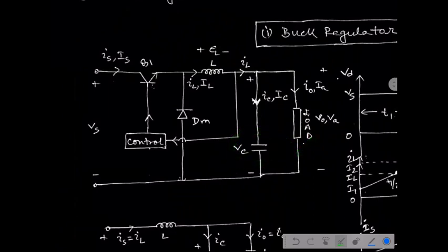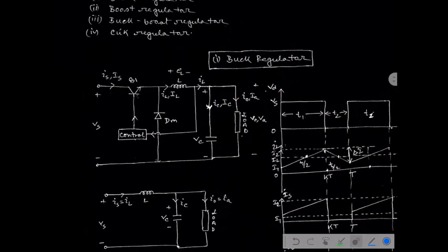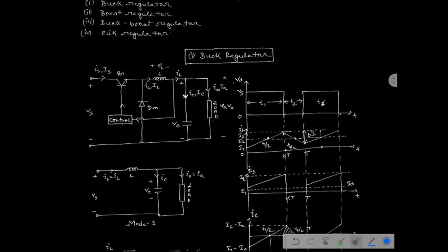When the inductor current gradually increases to the maximum value of 70 ampere, then 50 ampere is delivered to the load and the remaining 20 ampere flows to the capacitor. Then the capacitor starts storing energy inside it, that is, it is in charging mode. This operation can be well described by the numerical example.